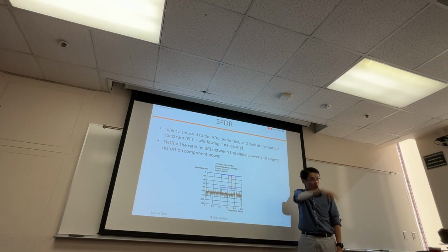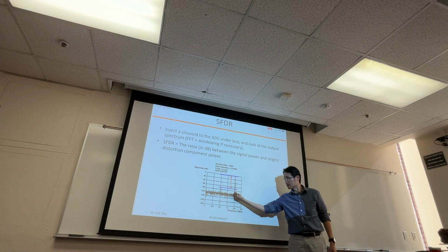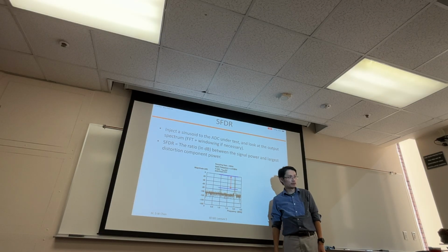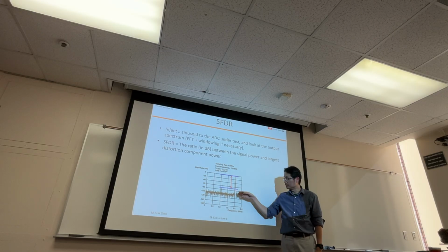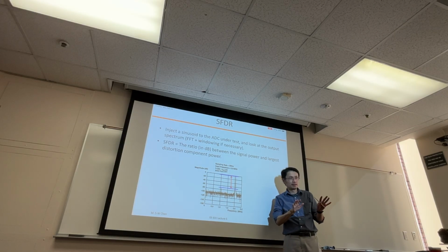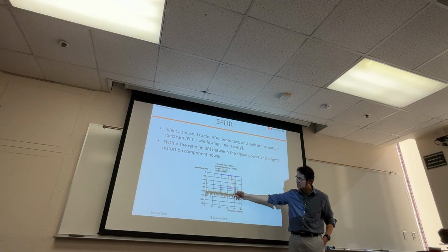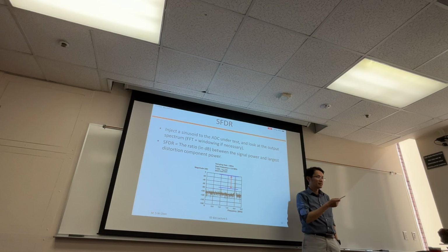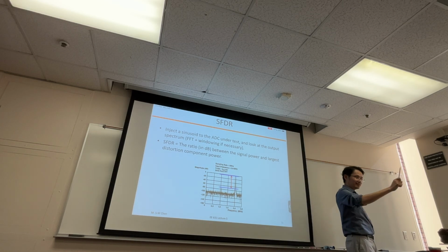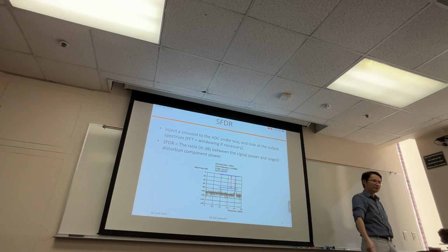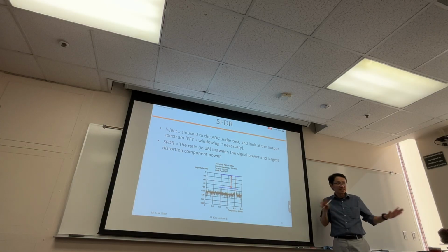If you see a single tone without this little skirt right here, what does that mean? Assuming that they are not lying, if somebody shows you an ADC output with a single tone, they used an integer multiple of the input period, so they are not applying any windowing, which is fine.